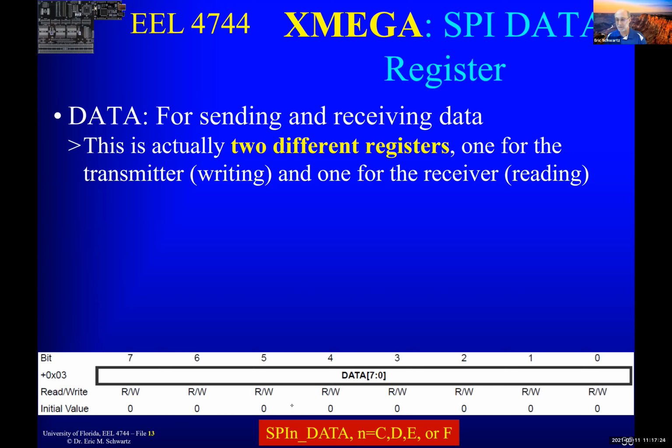Much easier system to use than the UART, but now we're going to tie to this an external part in your lab that's called an IMU, Inertial Measurement Unit. And this IMU, it's a big data sheet, and there'll be several pages that you'll need to read that are specified, and more that you want to at least skim that is specified in the lab document.